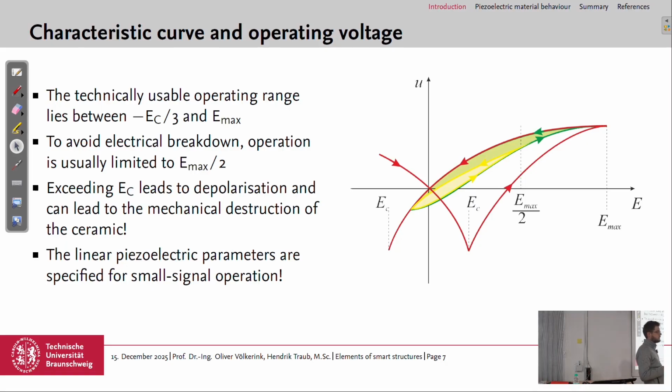How can we calculate it? I'm not sure if we can really calculate it, but it's always specified for the material, so you know it from the data sheet of the material. And you also see it if you do the experiment. If you increase the field above Emax, you would get here a straight line. So the displacement or the strain would not increase anymore. So if you increase the field and the strain or the displacement does not increase anymore, then you have reached Emax.